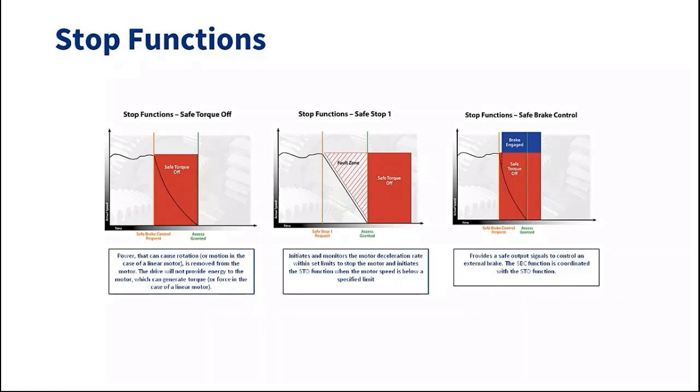The brake is a single point and it only has inputs, no monitoring. So we don't get a very good rating on the safety side if we have a vertical load that's holding, or some sort of static energy that could be introduced if it were to let go.